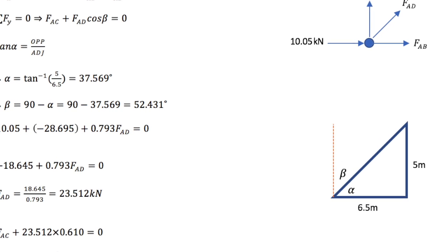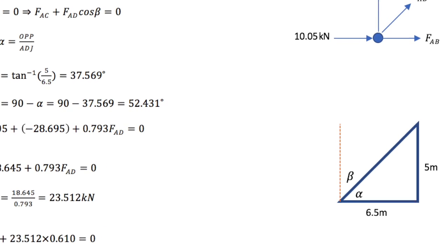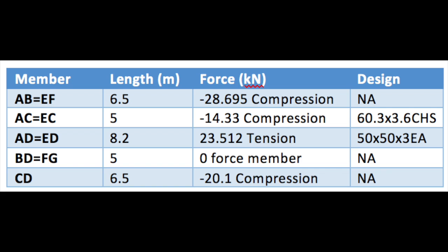The negative and positive values meant that the member was in compression or tension respectively. These values found enabled our group to select the correct bracing design to support compressive and tensile forces acting on the structure. The roof bracing is supported by the wall bracing. The reaction of the roof bracing is in fact the lateral force used to design the wall bracing. Again, equilibrium of a body and joints was used to determine the correct bracing design.